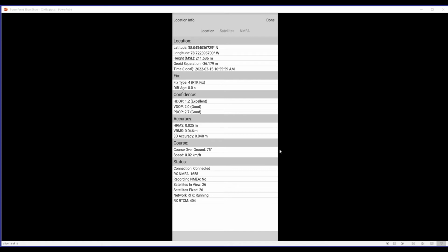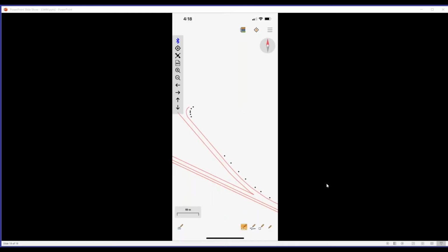As I move on to continue recording points, and what I did was there were, you know, survey stakes out in the field, and I walked along each one to record the locations at them. As I move from one to the other, I always like to just pop into my location info screen, make sure I'm seeing information relative to what I expect as I'm moving along. But other than that, I would walk through. I'm not going to show us collect every single point out in the field today, but I would walk along, record those points in the same manner, and we'll show them here when I completed that work on the map. So as I moved along to each survey stake and recorded a location for them.